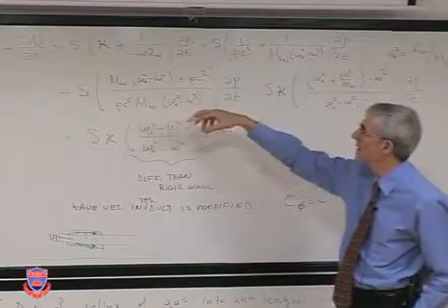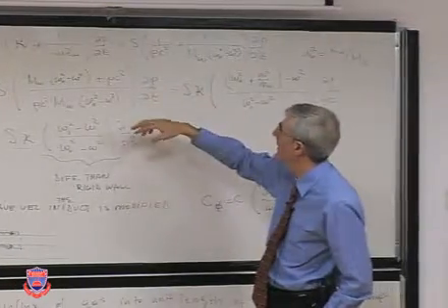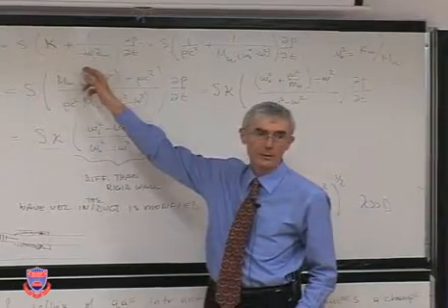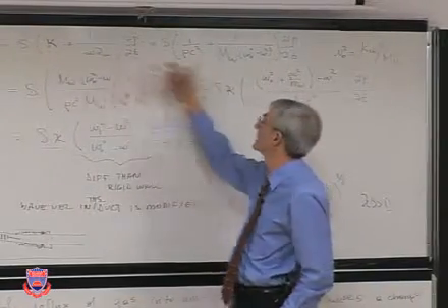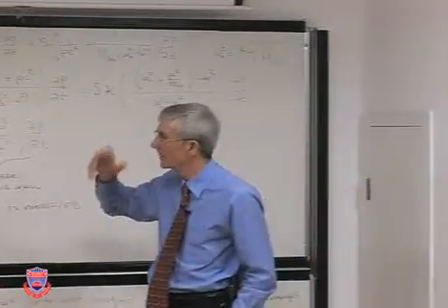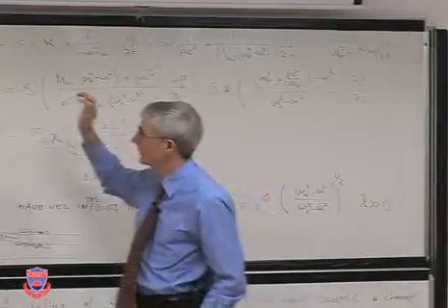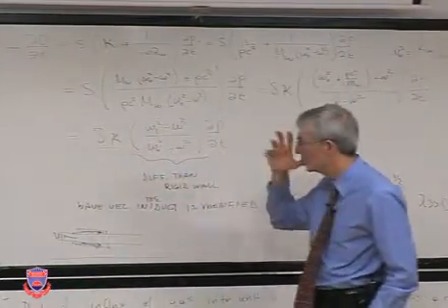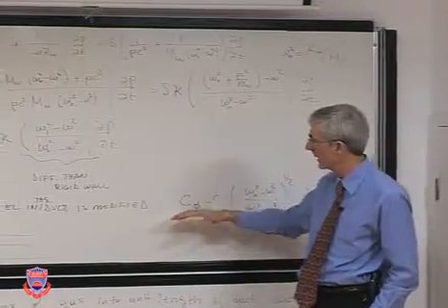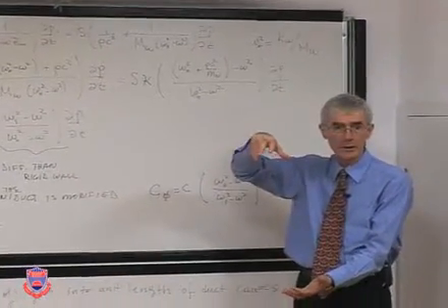Here we did a physical approach, saying that we need to take into account both the stiffness as well as the inertia for a complete impedance. We did not include any damping in this because it would have minimal effect actually, but you can just include it in here. And that gave us the notion that the flexibility takes some of the energy away.